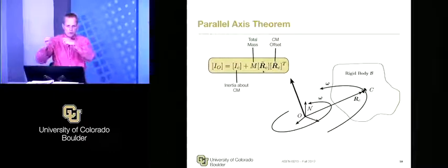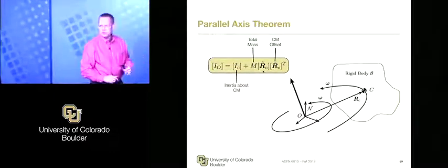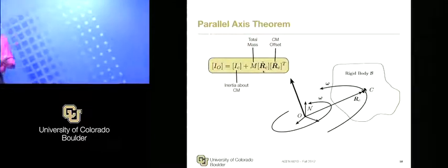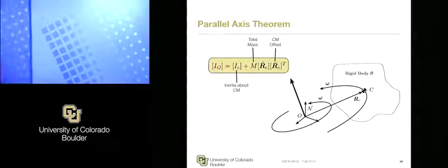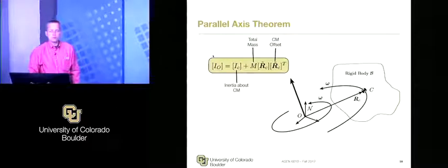When you do these RC1, 2, 3 vector components, right? That's probably the biggest source of error applying the transport theorem, is you're mixing up coordinate frames when you're adding up the contributions. Just make sure they're in the same one. And that'll give you the inertia here in terms of whatever frame you picked to express all these things, right?